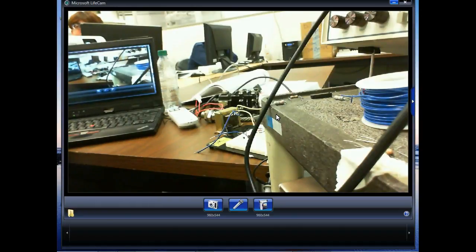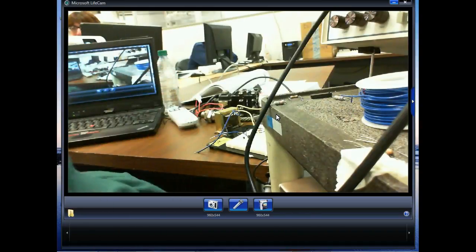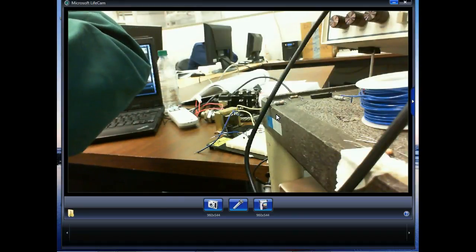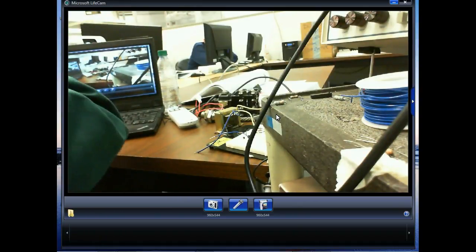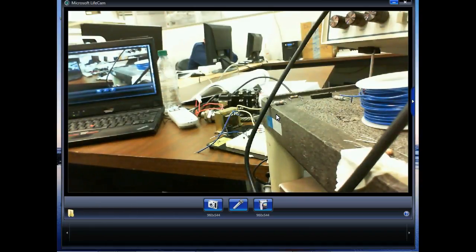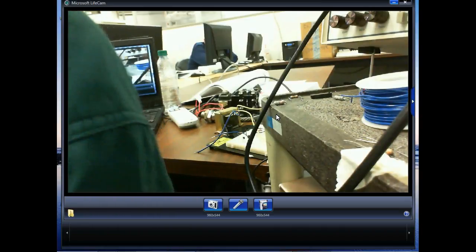So I'll send this around. Normally we wouldn't handle this board directly with our hands, especially the bottom. You can handle it, but you'd handle it on the sides. As soon as you put it on the bottom, it doesn't mean you are going to damage it, but you could easily. So we'll look at MOS technology later on in this class, and we'll look at some of the static guards that we go by just to prevent damaging them.